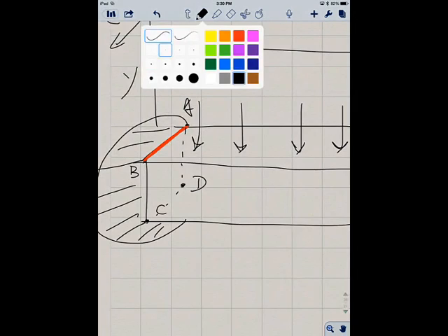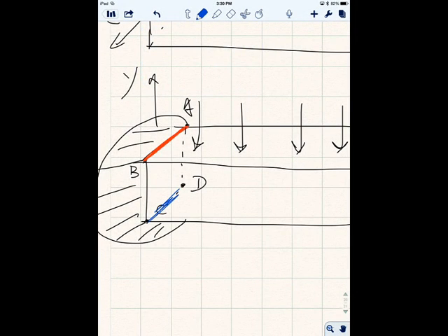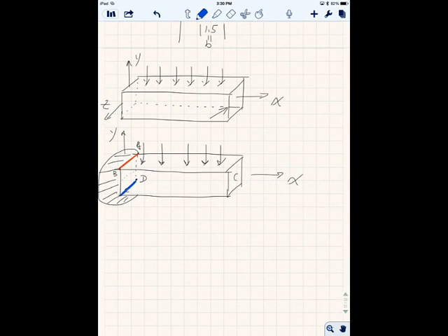CD, right? Very good. Should be CD over here because it's trying to push into the wall, right? Because in the center, at the neutral axis, is nothing, right? Top will be on the tensile, bottom will be on the compression. So of course, the further it is away from the neutral axis, the more stress it'll be, right? Okay, so very good.